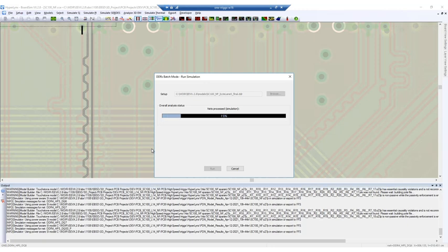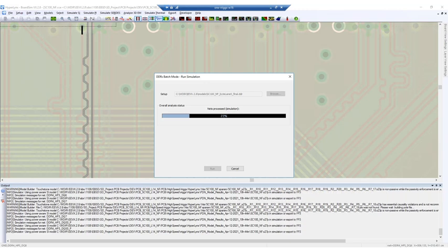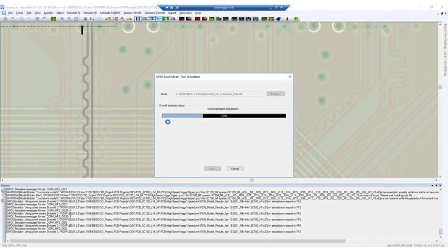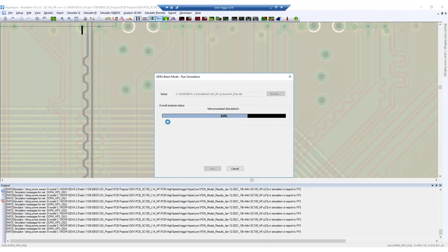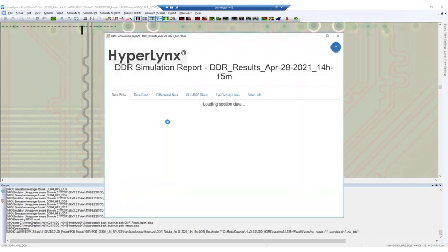The extraction of the S parameter for the power-aware model took a while to solve for, and as such, this simulation takes a bit more time to run because of the complexity of the model. The results and insight we get are well worth this time and effort, because if it passes, then we know our DDR signals will have a better chance of behaving as expected when fabricated.